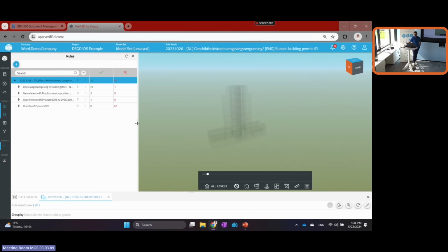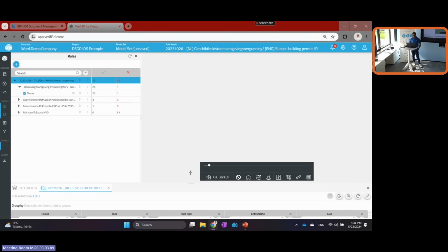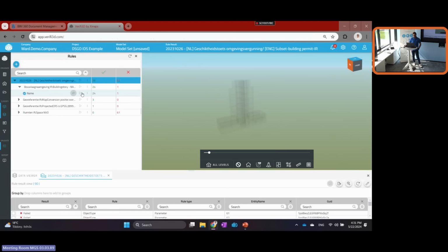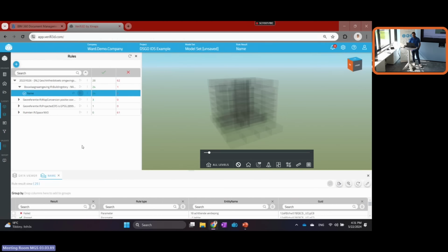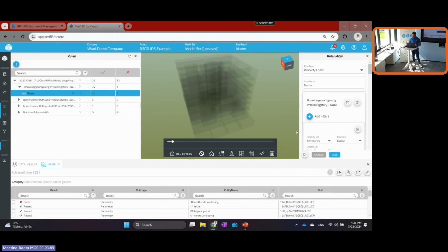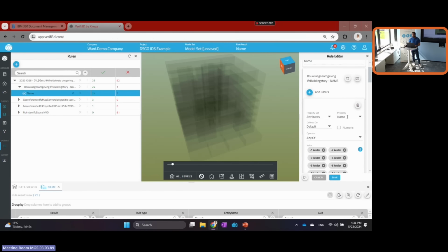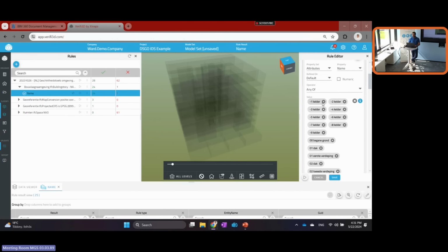Now in this model, you can see that we have some discrepancy. The first one, the IFC building story, we see that there is one level that is not named according to the building permit. If I just reapply these results, I can run it one more time. There you go. We have a failed entity over here. So if we go to the check, we go to edit.